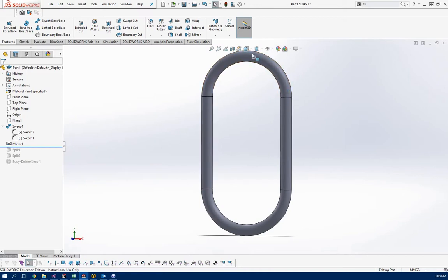So if I had a fluid inside this area, for example water, the hot area is going to make it evaporate and boil, and steam is going to go upward here, and when it reaches the cold side here, it's supposed to condense and go back. And this is basically a heat pipe.